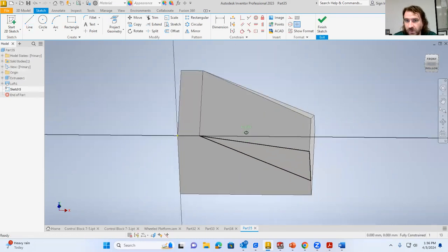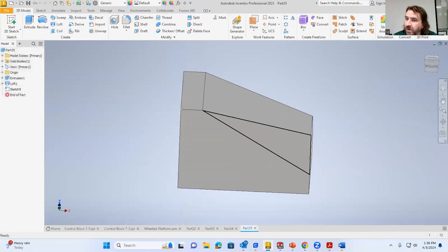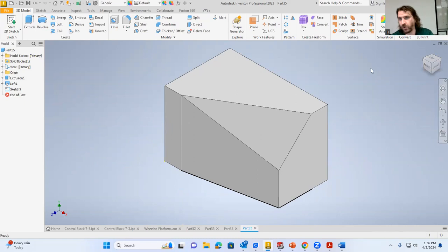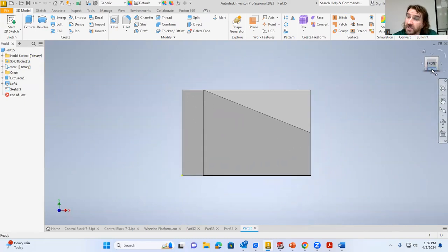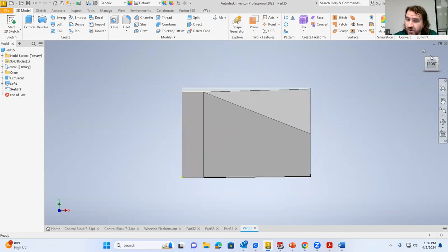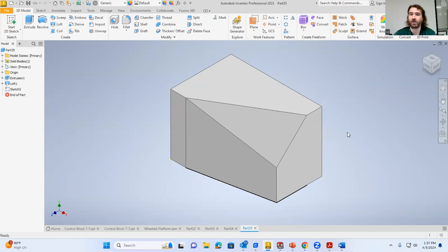There we go. Okay. Don't know what Inventor was doing there, but we just went backwards a step, went forwards again. And that's what you have to do sometimes, because the lofting tool can be pretty temperamental. So we want to make sure that our sketches are accurate and exactly what we need, and nothing additional. We want only what we need there.